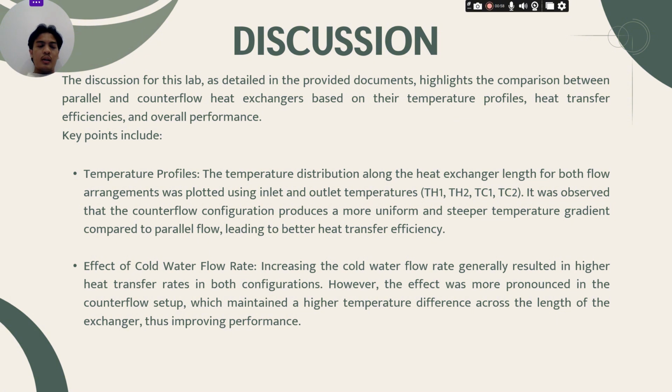Second, effect of cold water flow rate. Increasing the cold water flow rate generally resulted in higher heat transfer rates in both configurations. However, the effect was more pronounced in the counterflow setup, which maintained a higher temperature difference across the length of the exchanger, thus improving performance.